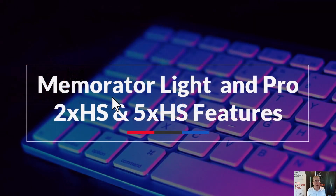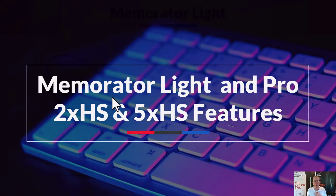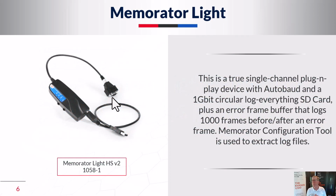So off we go. I'm going to get through pretty quickly a little bit about some specific hardware, and then we'll get into the software end of it. Some specific hardware from Kvaser would include, first of all, the Memorator Lite, which is an easy to use, no configuration necessary, 1 GB logging device that will also log 1,000 frames before and after an error event. There's no configuration, baud rate is detected, and it logs the data. It's that simple.